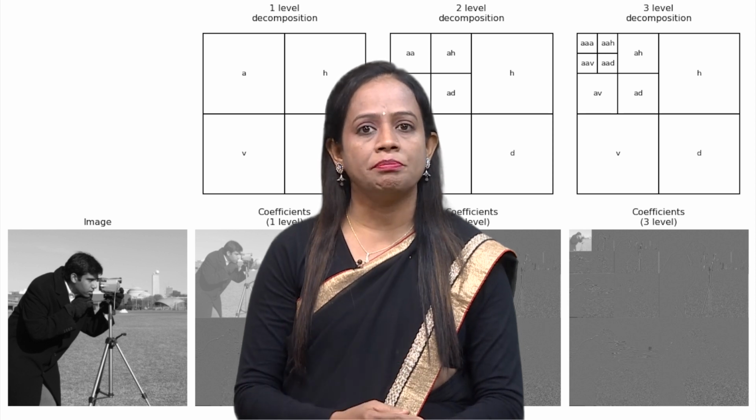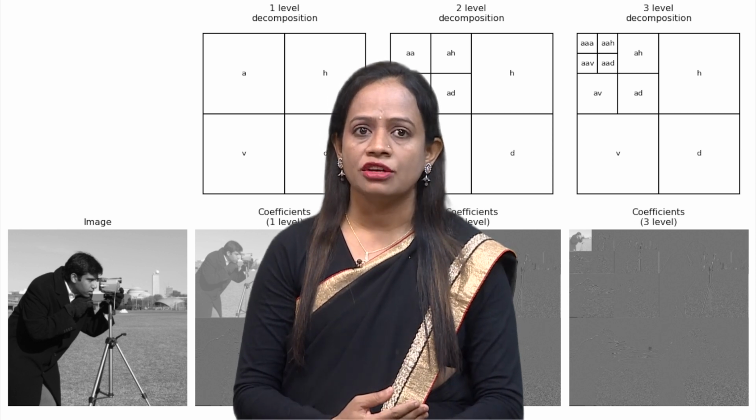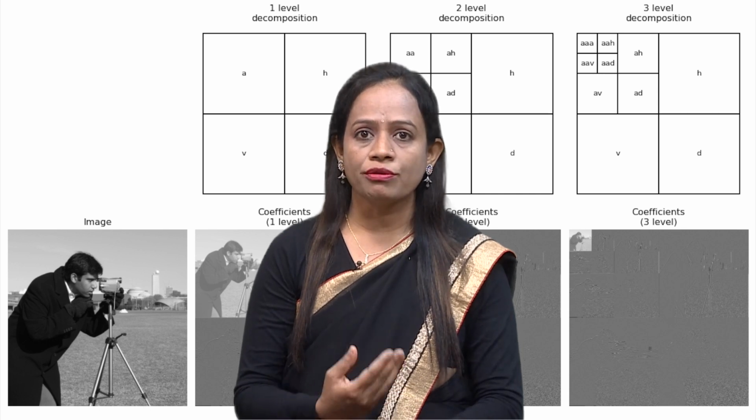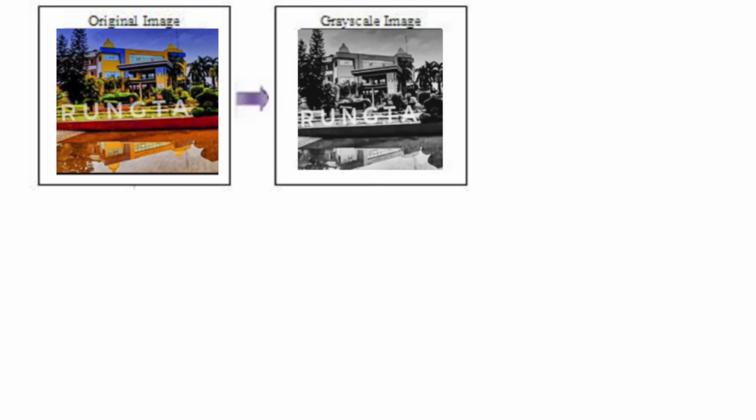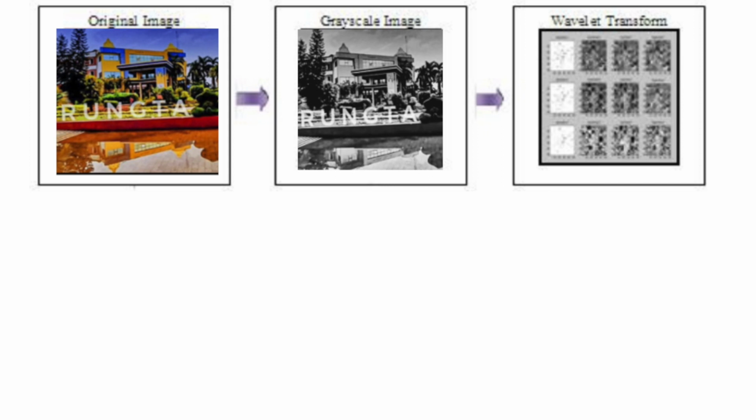Figure 1 depicts the step-by-step method for image compression transformation using the wavelet algorithm. The first step is that the original image is embedded into the system. Then the system will transform the image into grayscale to minimize the storage size on the disk. The grayscale image goes to wavelet transformation, with either first, second or third level of decomposition.